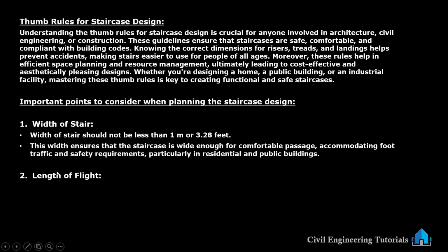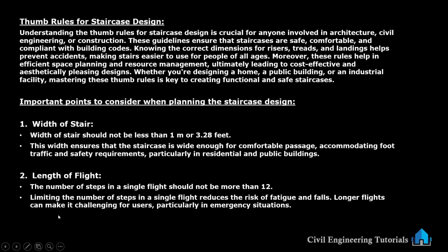Then length of flight. The number of steps in a single flight should not be more than 12. Limiting the number of steps in a single flight reduces the risk of fatigue and falls. Longer flights can make it challenging for users, particularly in emergency situations.